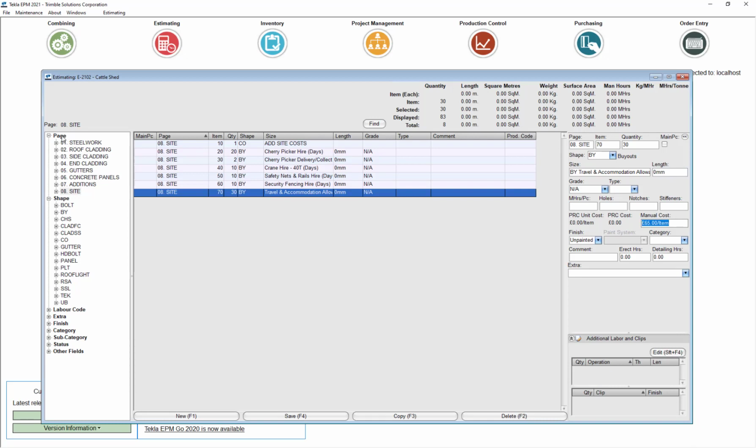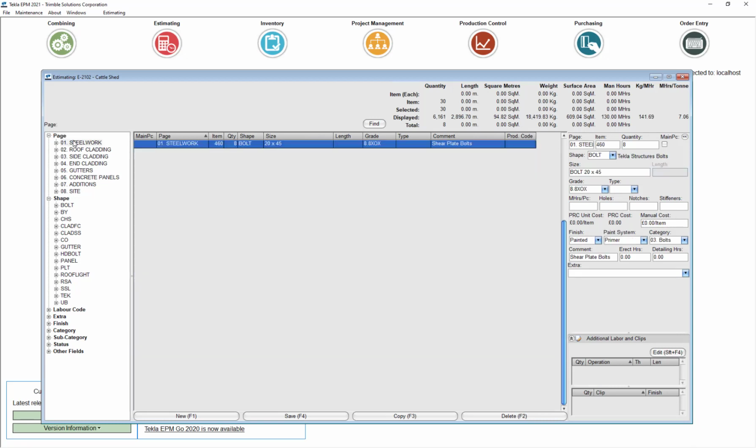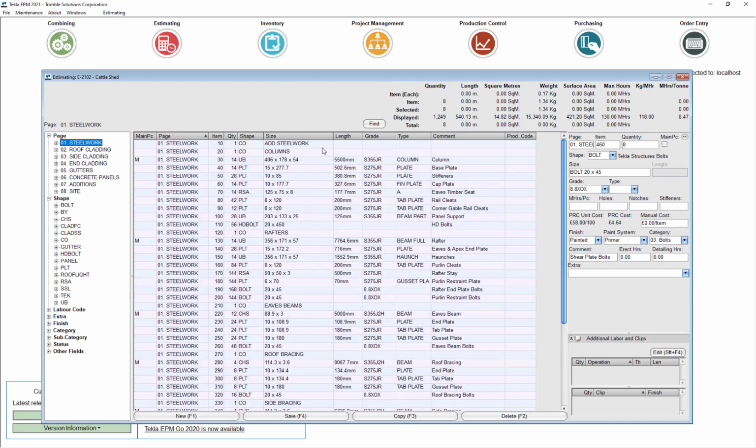Okay, so that's the takeoff process, and obviously we've got an awful lot of detail in there, and you might ask, well, I've got a very simple spreadsheet now. It gives me a cost. Why do I need this level of detail? And really, the answer is that this can drive your efficiencies and your accuracies. So if the cost of one material changes, it's very easy to adjust that. You haven't got costs wrapped up with one another.